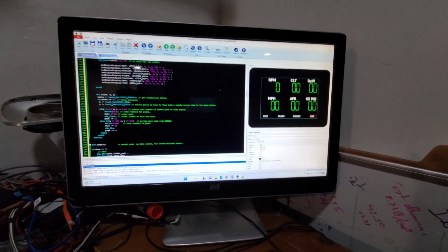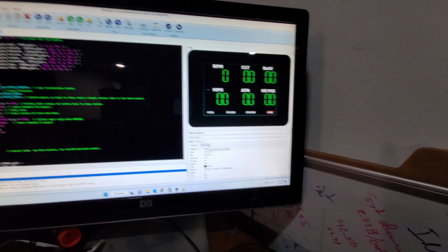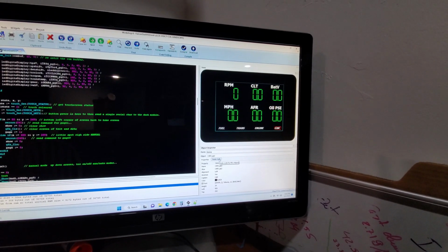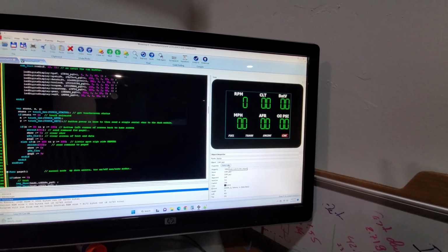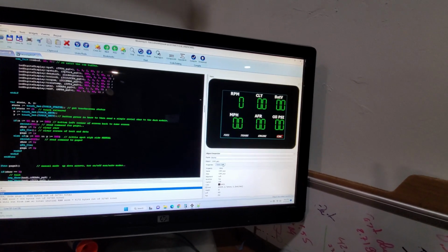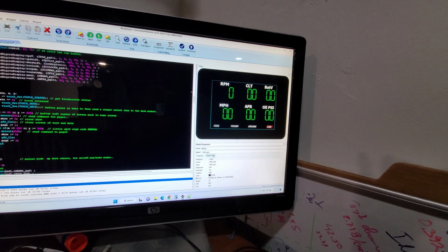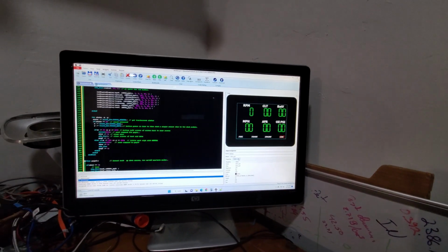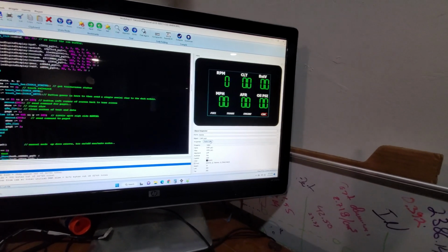All right. So, because I like to punish myself, I decided to extend the range of values that I can display on this touchscreen display. So what I've done is I've added a pressure transducer to the oil pressure port on the motor. So now it allows me to see oil pressure. So what I wanted to do is create the CAN bus message from the ECU to the dash module to then send over serial data to the display to display the oil pressure.